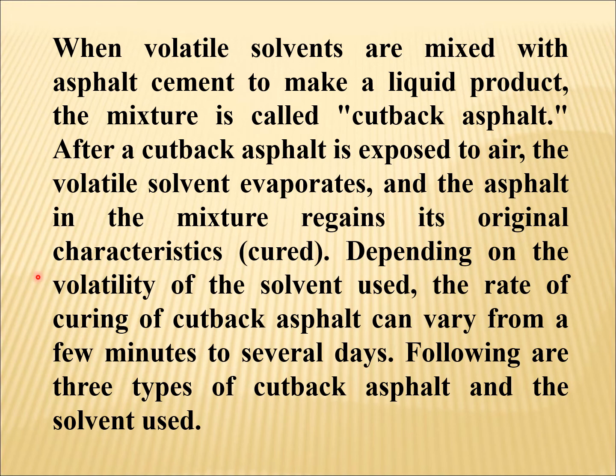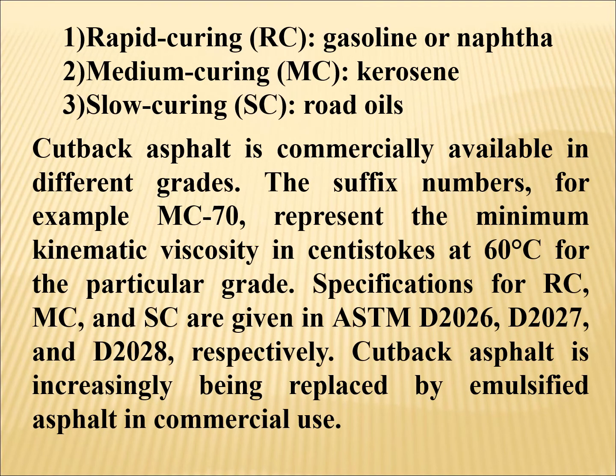Depending on the volatility of the solvent used, the rate of curing of cutback asphalt can vary from a few minutes to several days. Following are three types of cutback asphalt and the solvent used. Number one, rapid curing, RC, and gasoline or naphtha is used in that case. Number two, medium curing, MC, and kerosene is to be used in that case. And the slow curing, SC, the road oils are to be used.